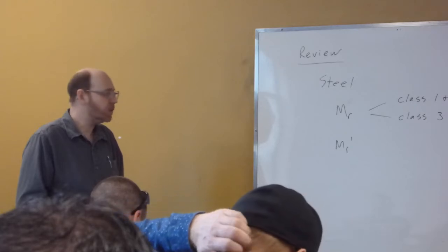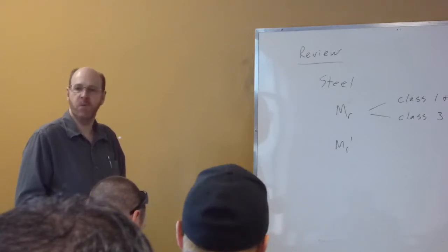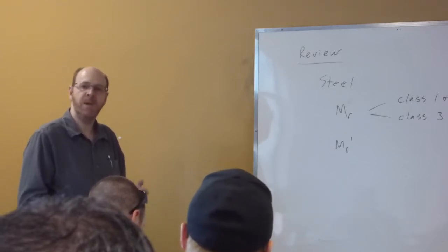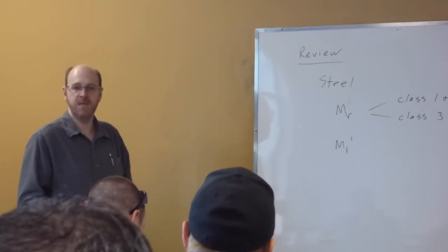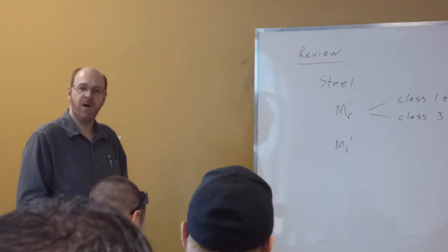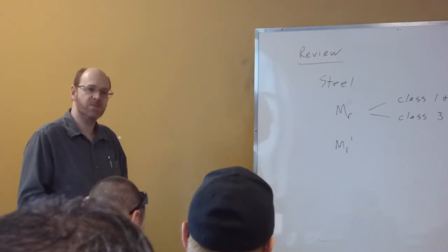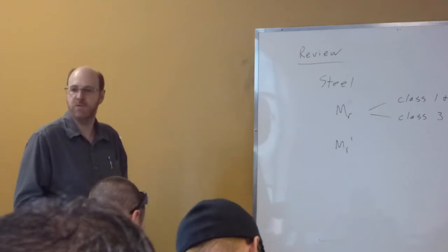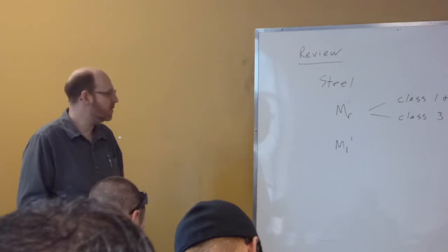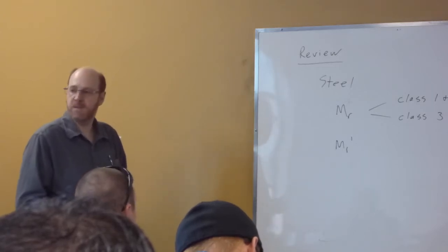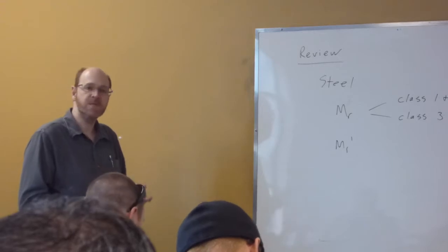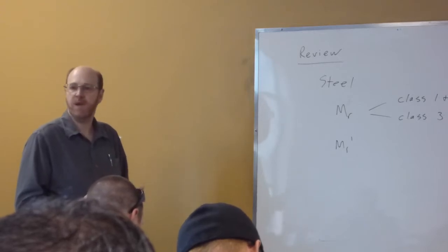And then there's also our beam loading tables, where there's an approximate deflection based on 240 MPa. So we calculate what the actual stress is and calculate our deflection based on that approximate deflection multiplied by the ratio of actual stress to that 240 MPa. Right, so several different methods we looked at for deflection. So just like we had with our wood beams, we have moment resistance, shear resistance, and deflection requirement.